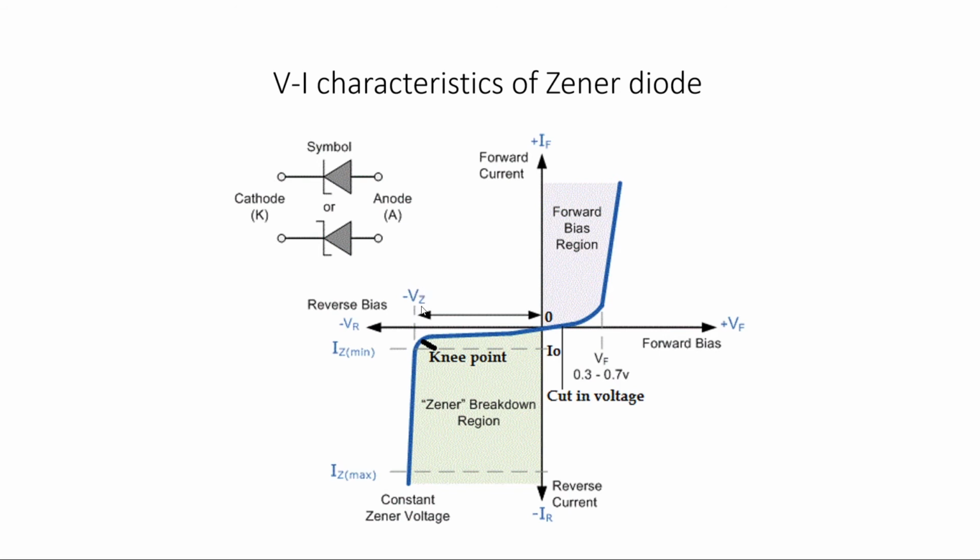Now this voltage will be varying for many diodes. Standard voltages are 5 volts, 12 volts. What we use in our electronic applications, mostly we use 5 volts. Zener diodes are also used for triggering purpose in thyristor to control the triggering angle and triggering point.